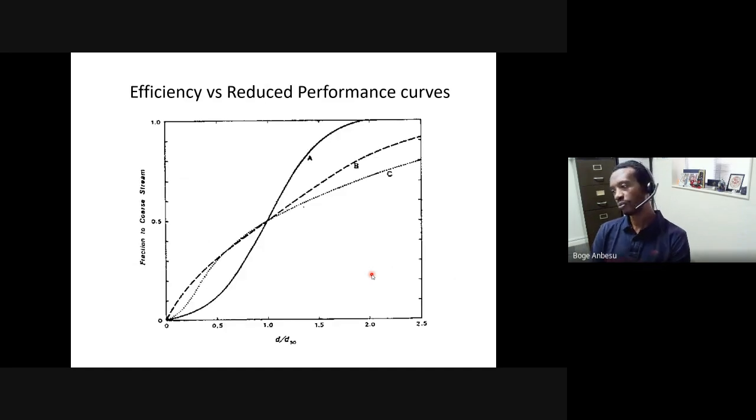So typically what people do to optimize a cyclone performance is you look at two things. Either you would change the feed water composition, okay, so you reduce or increase feed water going into the cyclone and try to optimize that. Or the other thing you do is you play with the pressure. So pressure can be increased or decreased. As you increase or decrease the internal pressure, you would then have the opportunity to either drag finer particles to the wall and reduce your cut size. With that, you may also improve your efficiency of hydrocyclone or a classifier performance. So it all depends on those factors.